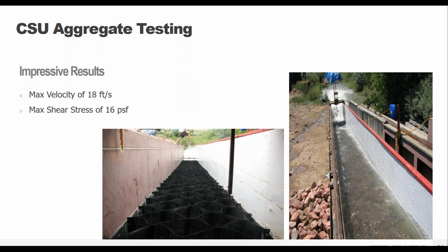But the main objective here was the determination of reduction in riprap size due to the GEOWEB system. Also, something to keep in mind is that vegetated channels can only withstand water on an intermittent basis, otherwise your grass is going to flood and die. So if you do have continuous flow, aggregate is going to be the right option. Even if it has a lower max velocity, it definitely still has its place on why you would choose it for protecting your stormwater channels.